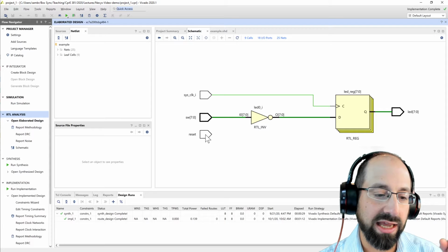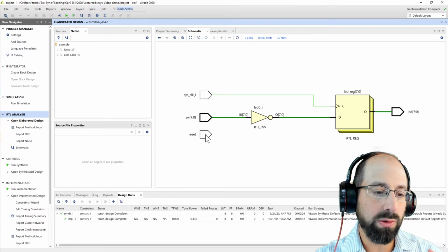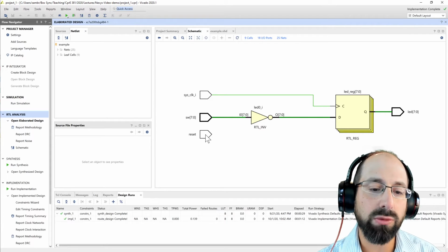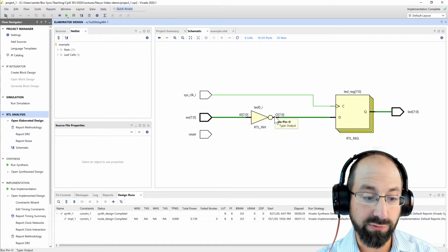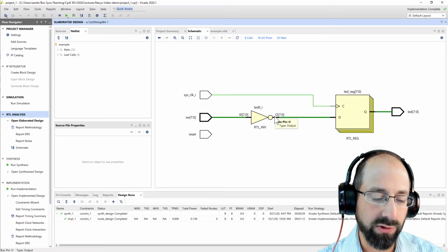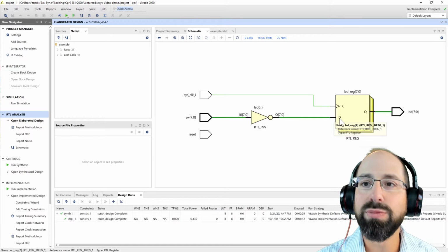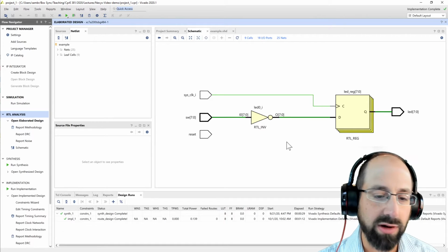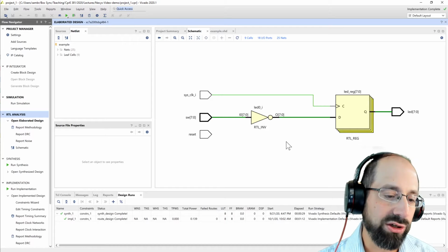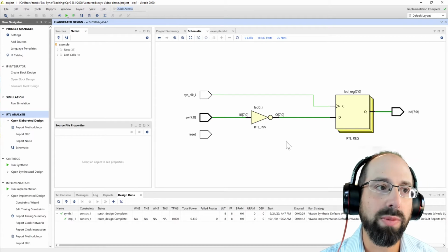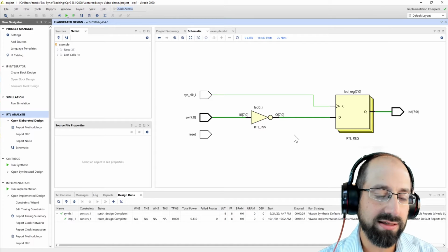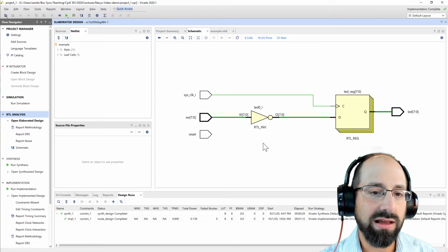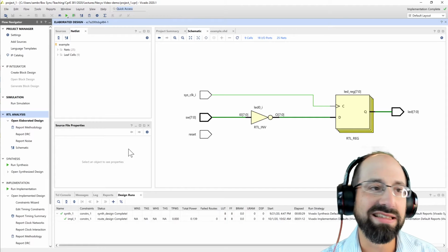It allows you to understand from source code to a behavioral model. And the behavioral model would be things like you have something that's effectively an inverter, so you have to invert based on the standard logic function for implementation of not, and then that would be connected to a register because you're storing that at the rising edge of the clock. It's analyzing your design and giving you a behavioral model back out. The manufacturers and the software developers for this call it different things. Xilinx calls it RTL analysis.